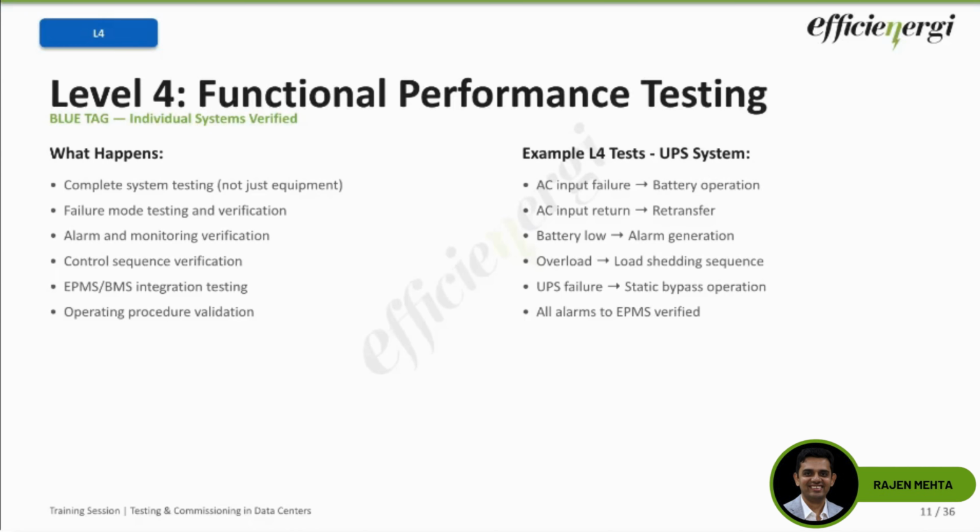Okay. Then you go to the sequence of operations. That's the document which you prepare at this stage, where you are validating that the overall system is operating as it should behave. So it validates whether the system is operating as per the sequence of operations script which has been defined earlier.